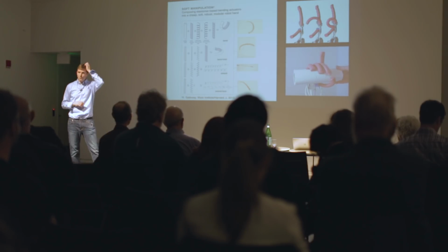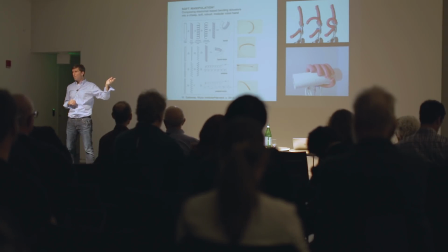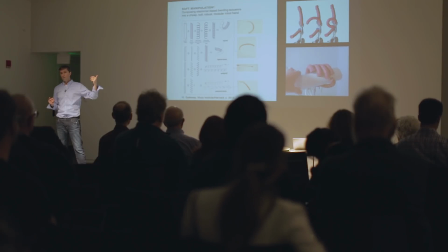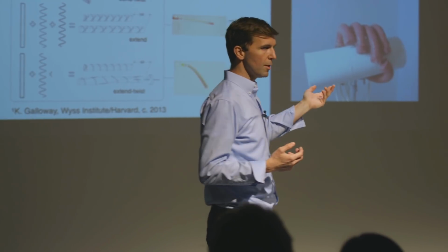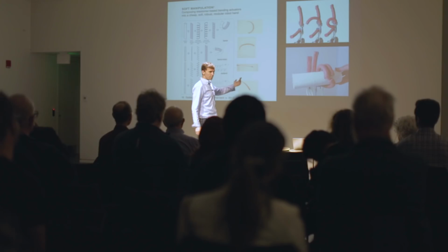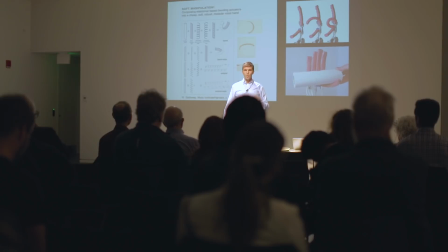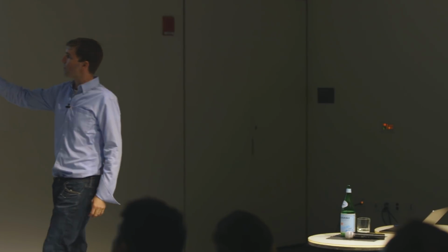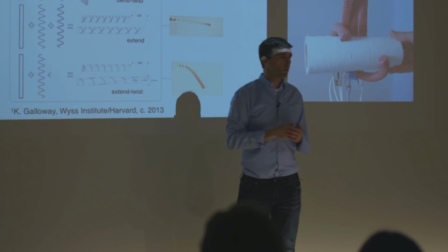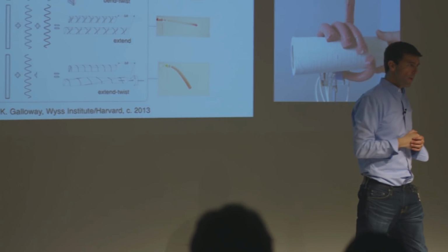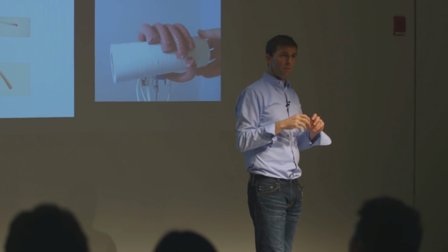We were doing this a few years ago, trying to figure out, if we're going to make robots out of soft materials, how do we make the core components? How do we make sensors and actuators? Very simple things. How do we make a motor equivalent but out of rubber? This is an example where it's just an elastomeric balloon that's being pressurized internally, and if you pressurize it, it'll change its shape. And one of the tricks that went in here is if I reinforce this elastomeric balloon with inextensible fibers or any sort of inextensible material, then I can get extension-bending coupling, extension-twisting coupling.